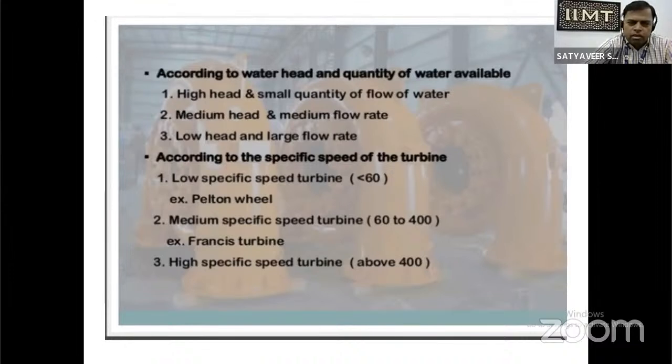If we talk about the other classification of the hydraulic turbine, then it is based on the specific speed of the turbine. Basically, specific speed is nothing but the speed of a geometrically similar turbine that will deliver the required power under a constant head.